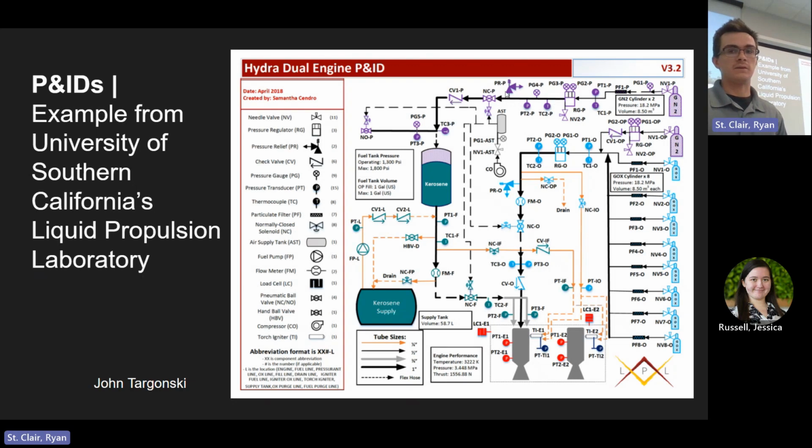Here's that pressure relief valve again. And it goes across this ball valve through a check valve. Obviously, they're concerned about some kind of backflow, and it goes through this line. It looks like there's some flex hose, and here it arrives at this kerosene tank, and it just pushes that kerosene down through this line. They've got a flow meter right here. They've got a nice legend. And then across that flow meter, they have some kind of flex line here, a ball valve, which I imagine